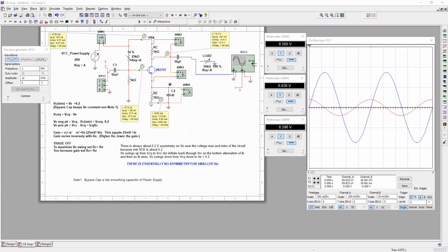So assuming there is no input, so we're in the quiet mode, we also call it the quiescent mode, there shouldn't be any change to our operating point once we fix the voltage divider. But in fact, transistors are very sensitive, and the beta factor, or HFE coefficient, that amplifies the base current can change with temperature. When it does, it's going to increase the voltage across RE.